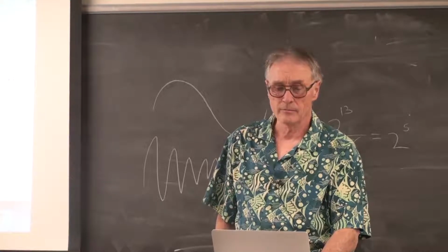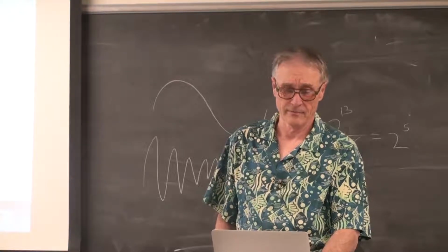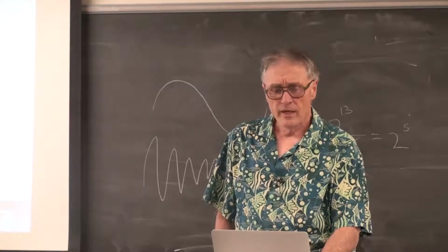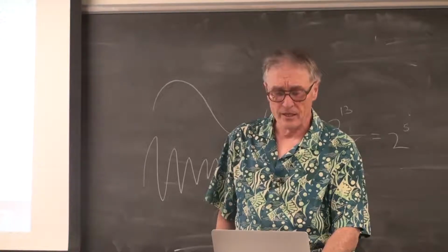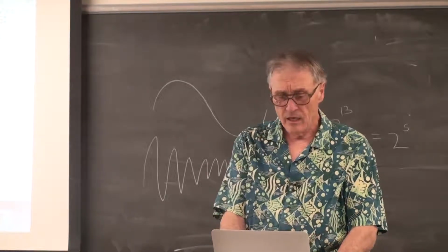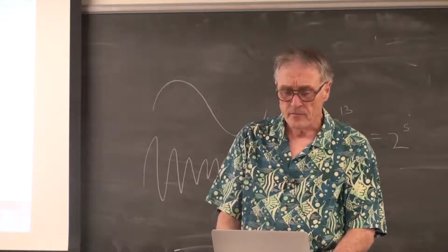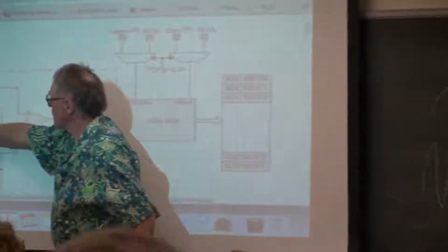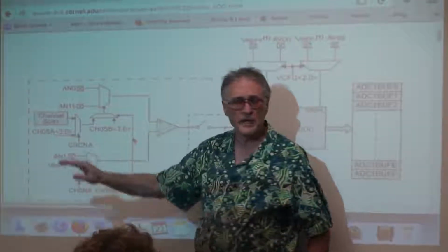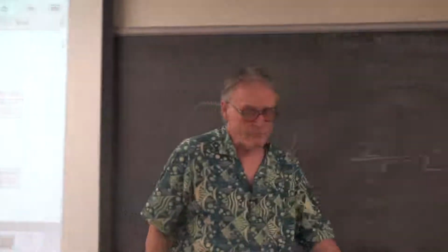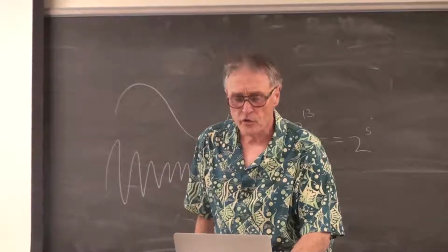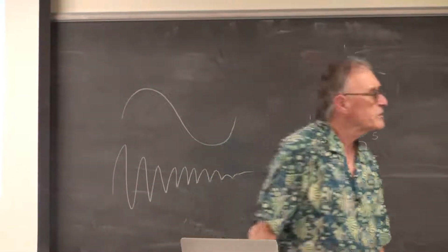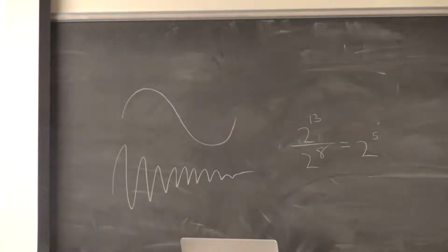Let's talk about ADC, analog digital converter. The ADC on this chip is a fairly vanilla analog to digital converter in the sense that it has a bunch of channels, AN0 through AN15, which map to random pins around the chip.